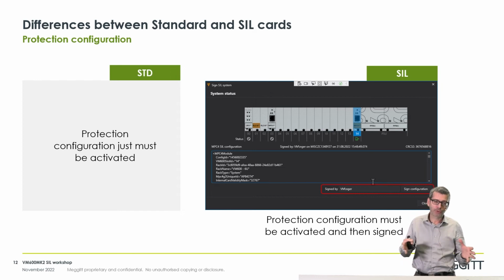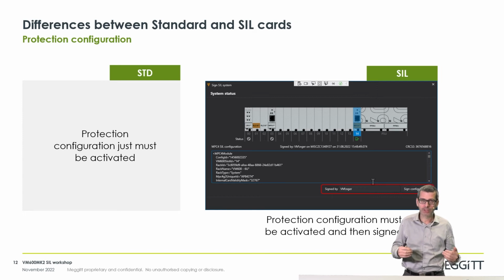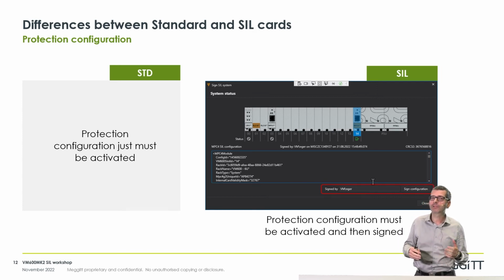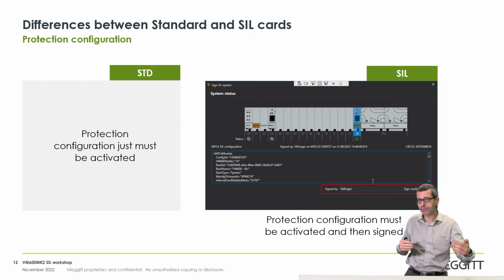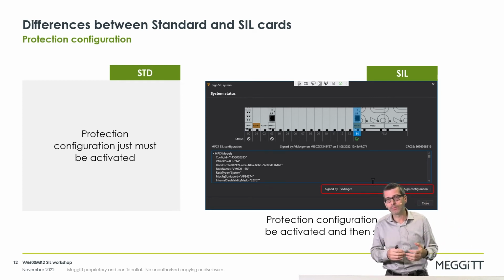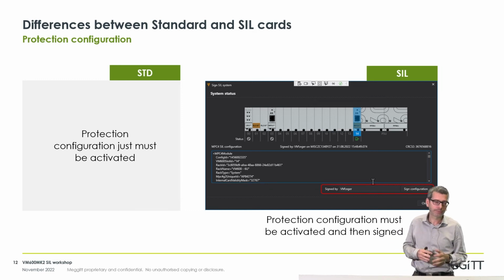A typical process would be to configure the card in the same way as we do for the standard, then inject signals and validate that the logic works as expected and everything is properly configured. That process might imply configuring the card several times until we get rid of all the potential issues. When that process is finished, there is one last step of signature.